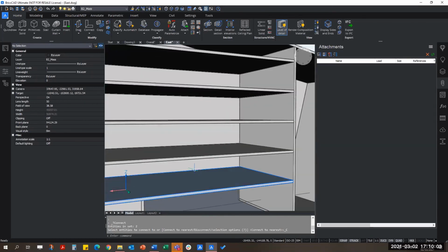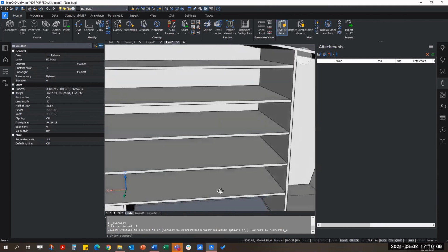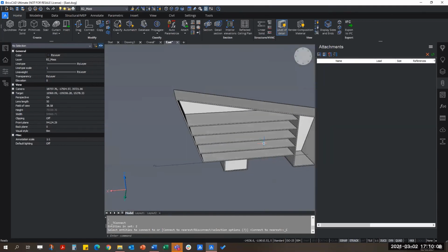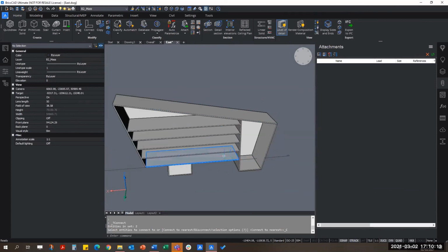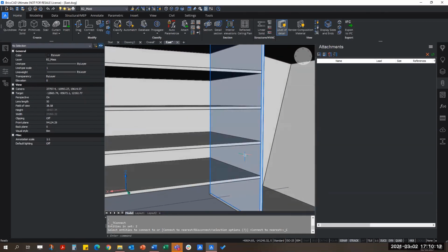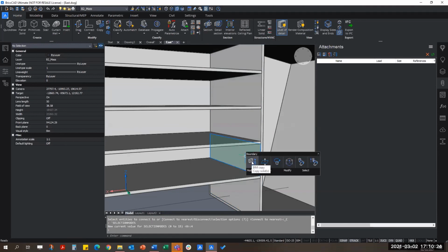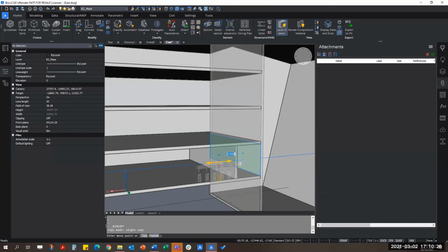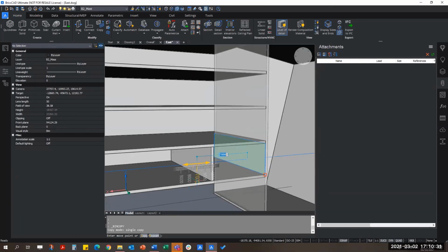And let's say I'd like to bring some internal walls in, but I'm not ready to bring a plan view or plan section, as we call it, through this floor plate in order to model that wall. So what you could do here is turn on boundary, select this, do a BIM copy, and you notice because I've just selected this boundary here, I'm only given this option to do it just on this floor and not the floor above or below.